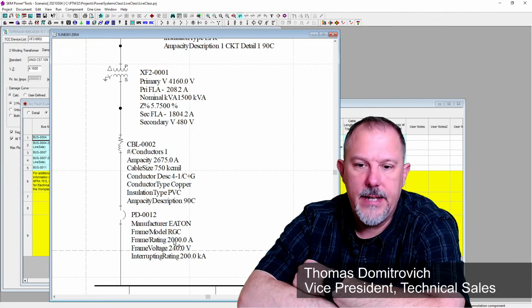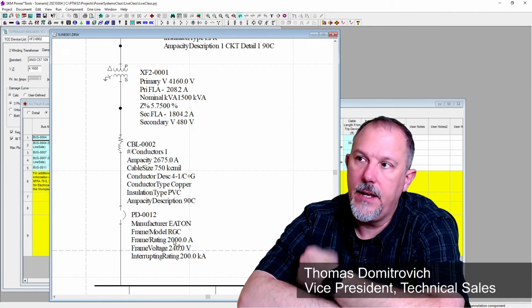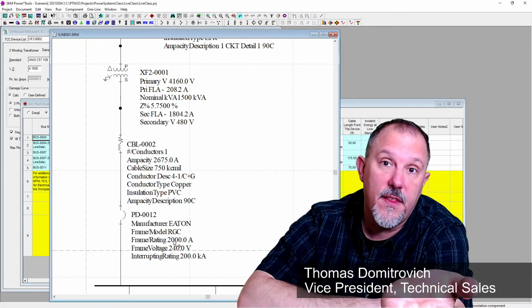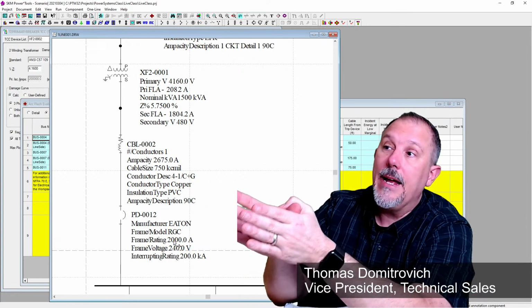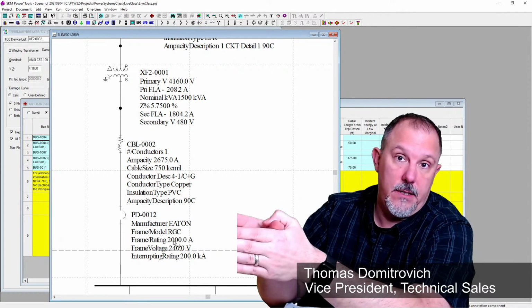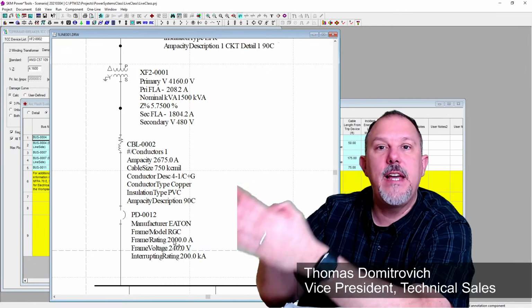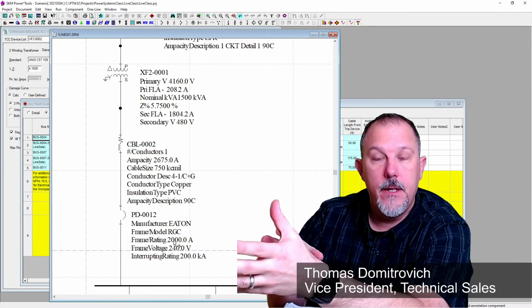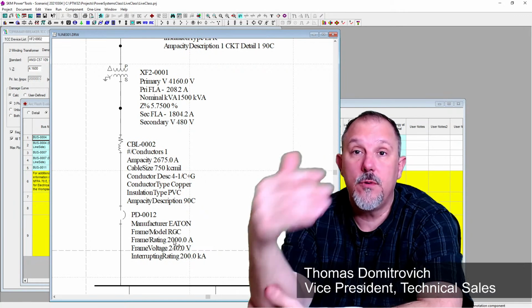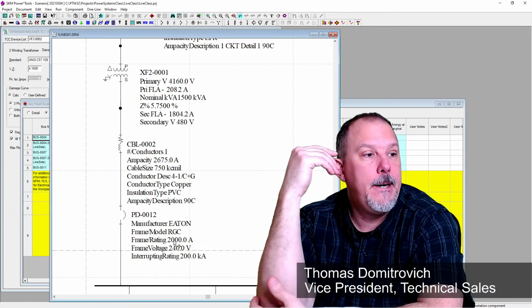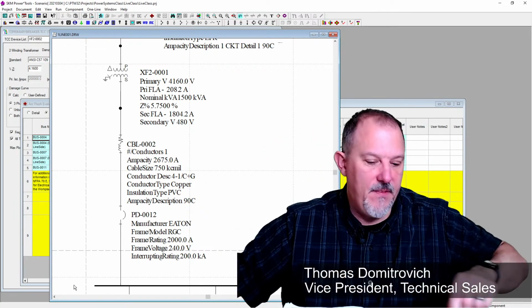Right, it doesn't care anything about that loading. And the other thing you can think about, I could buy a transformer with fans and get more kVA out of it by cooling it. And another important thing from a short circuit perspective, let me find it here.